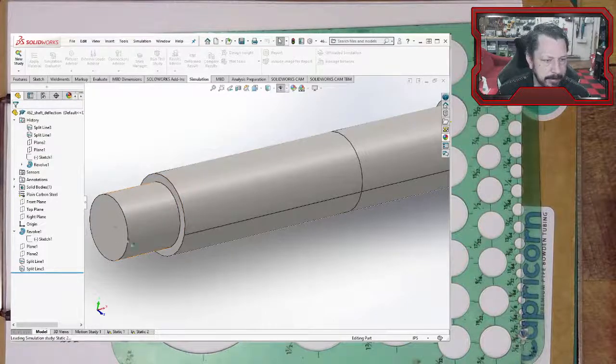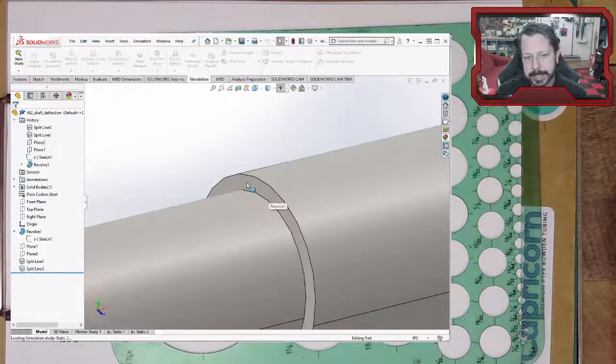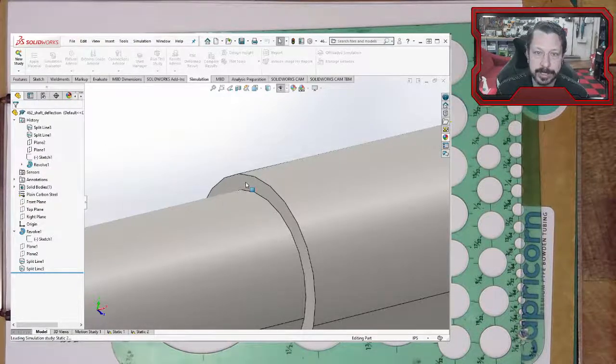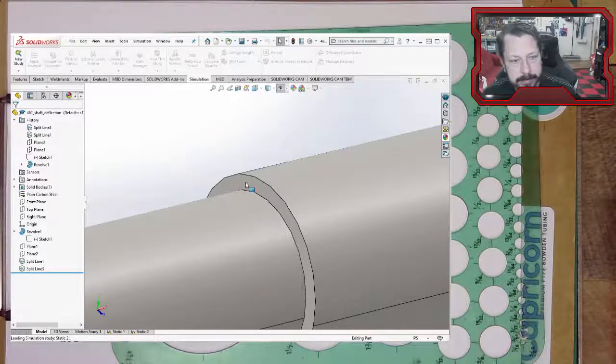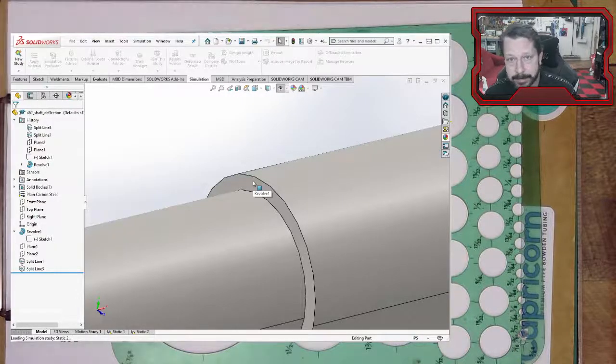I think this is a 1/2 inch diameter, and then this is 5/8, I think. Same thing over here. Now, this one's not as big of a deal because it's just up against the gear, which in this case, you actually do want the gear and the shaft to sync together. You want to be able to transfer torque. So if anything, this is helping me transfer torque. But it could be a little bit larger, but it doesn't have to be, at least not to locate the